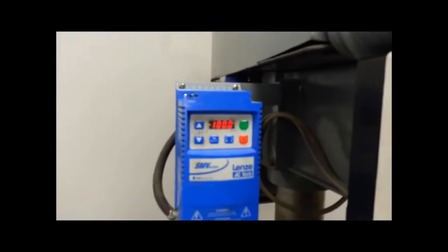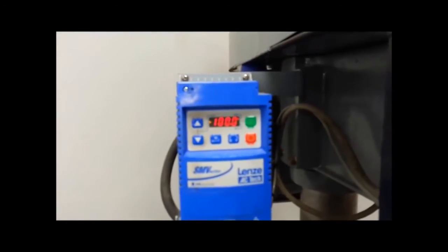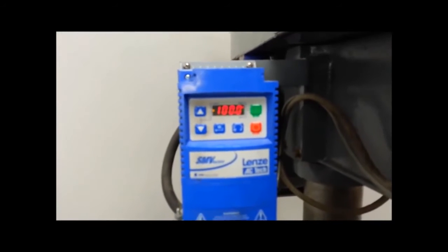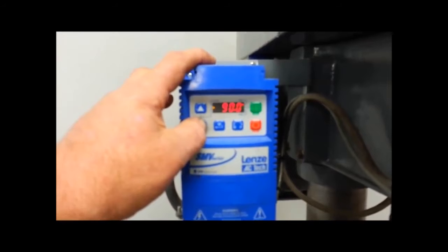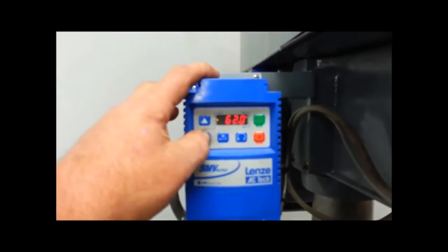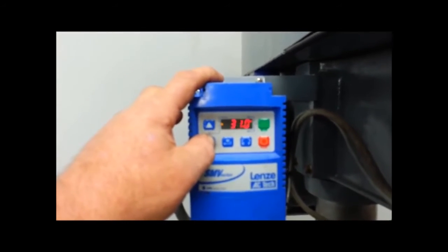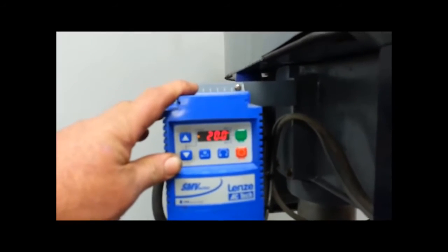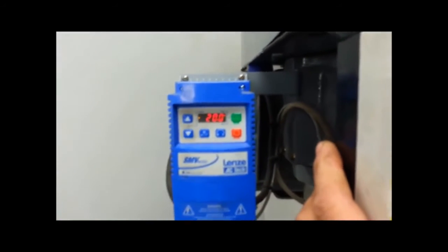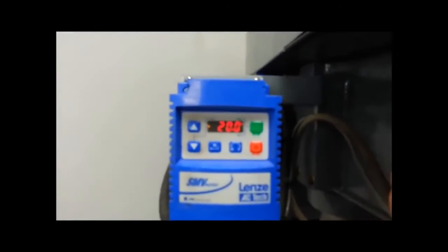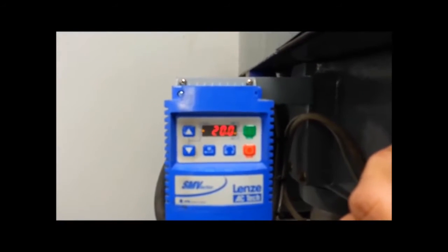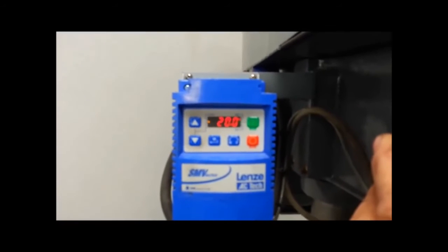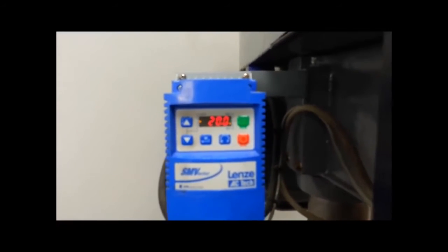That was a very fast ramp down and a very fast ramp up, but it changes directions very quickly. You can't even see it at the low speeds. I'm going to take it all the way down to the low speed, 20 hertz, and I'm going to apply a reverse command. It's literally almost instant. And if you're tapping, that's just what you want. You want to just stop that tap and turn it and get it going the other direction.